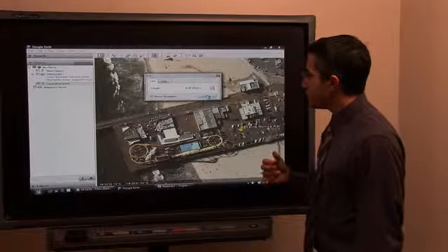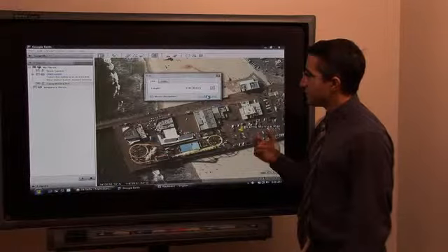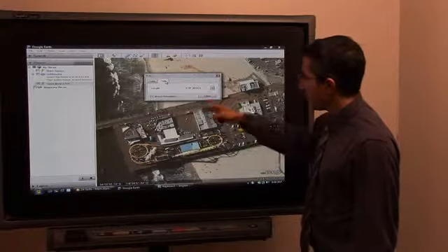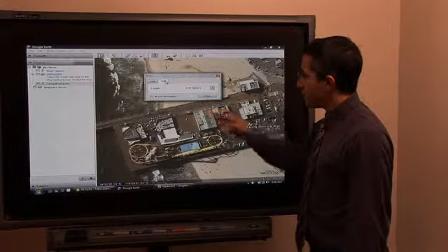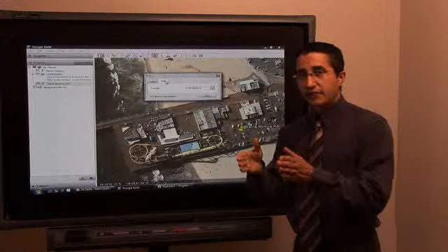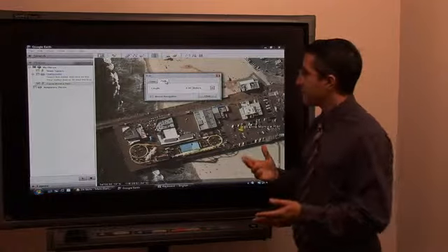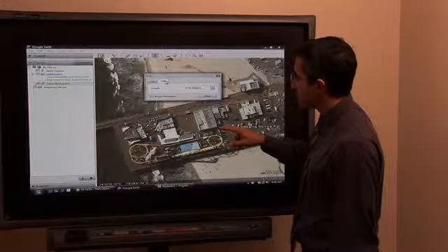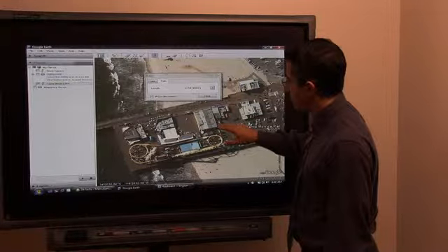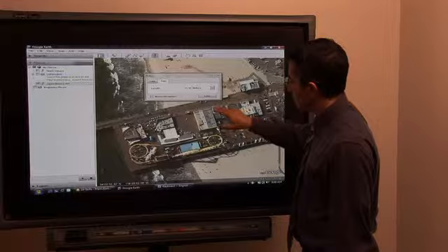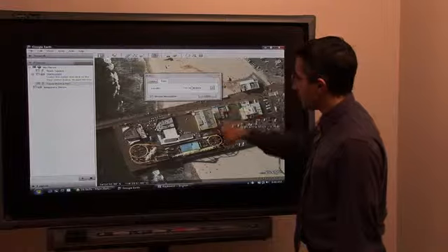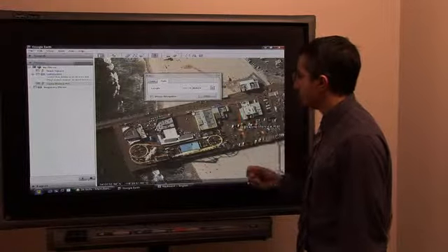Another way that you can do this is to measure a perimeter. So in order to get a perimeter, I'm going to choose path, and I'm going to select a building. In this case, it's going to be the arcade building that's right here. And notice that the arcade building is not exactly, well, it is a rectangle, but it's not exactly perpendicular, which is fine. None of that matters because I'm just going to go from one corner to the next. So in path, I'm going to click on the first corner, go down to the next corner, the third, the fourth, and then back up to the beginning. And as you can tell, I've created a rectangle up here, and it gives the results.